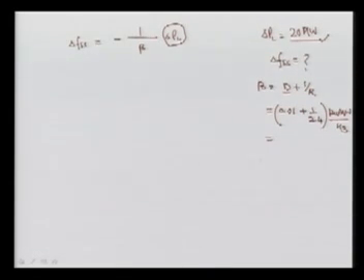So this PL will be your 20 megawatt divided by the base quantity, and this base was the rated capacity, which was 22,000 megawatt. So we are going to get here 0.01 per unit megawatt. We have to use per unit megawatt always, because here the value is the same, so that is cancelled out. So now we can get the actual value in hertz.